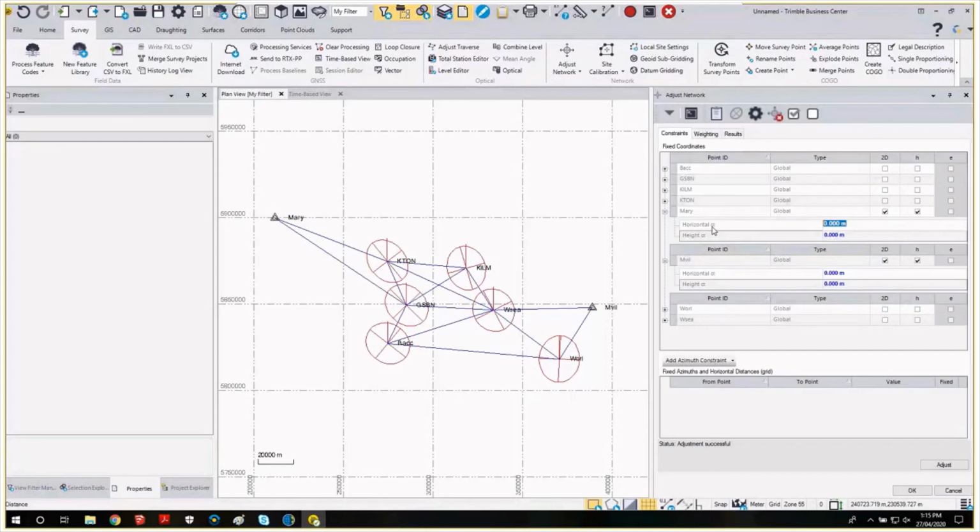It is standard that we report, or the ones that I've seen for government marks are reported at a 95% confidence interval. So in order to get back to this, we need to divide the error by 2.448, and that gives us our error as a 1 sigma value.